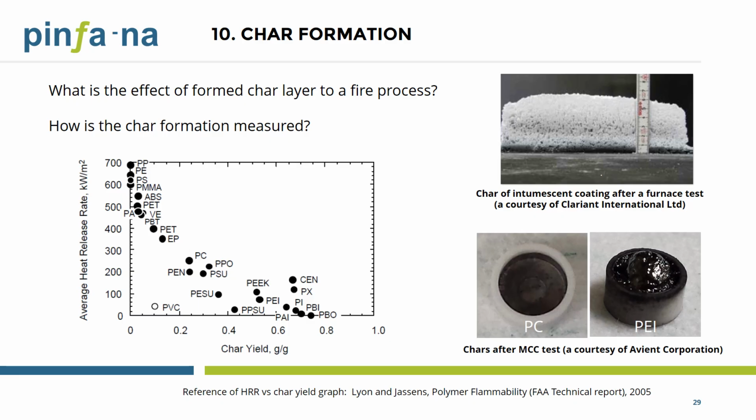Thirdly, a char layer can also be qualitatively characterized in terms of the sturdiness or porosity of the char. Is that a thin, flaky char layer or a dense, uniform foam char layer? If the char easily flakes off, it typically doesn't protect the underneath material.